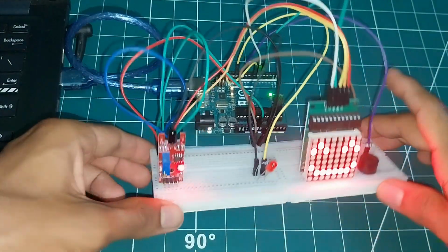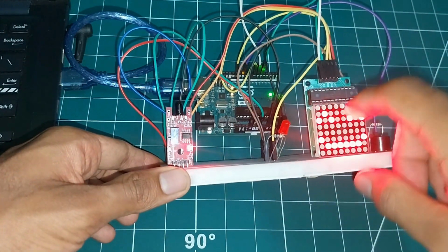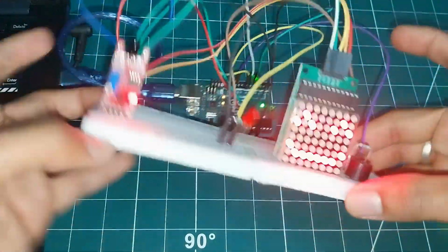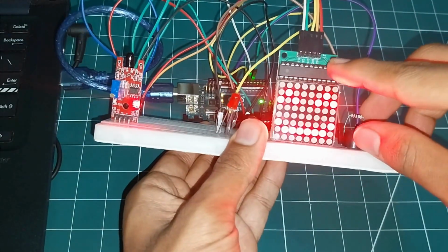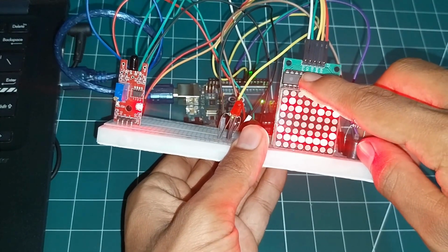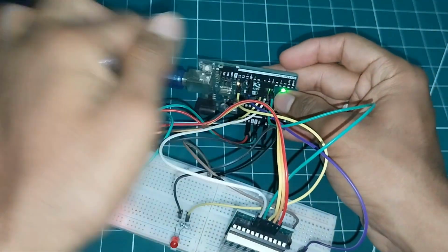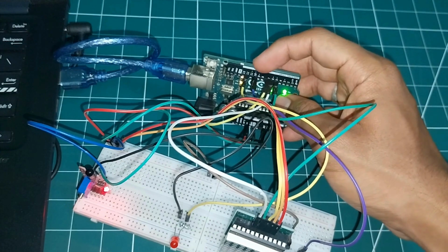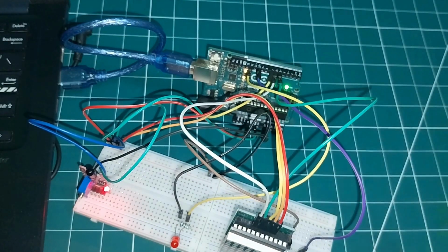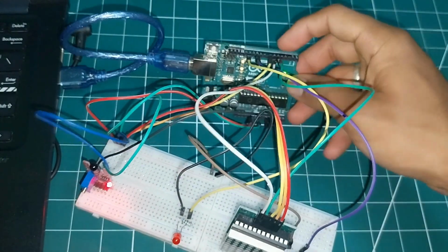So basically we have taken an A0 pin here, because we have the analog series of this 8x8 LED matrix, and we have many pins here on the 8x8 matrix. Two are common, that is VCC and ground, but DIN, CS and CLK are being connected to the digital pins, that is pins 5, 6, 7 and the 10th pin, and the 12th pin is for LED and the buzzer. So the 10th is for the buzzer and the 12th is for the LED.